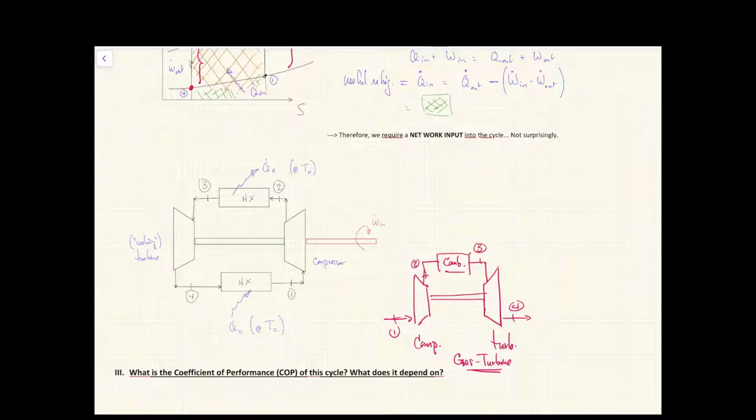So what we're going to do is take some of that air that comes into the turbine, tap it out at some intermediate stage within the turbine, and that's what we're going to use to go into the initial compressor. So the diagram that I have here is an idealized representation of a closed cycle doing this. But in practice, we don't have this heat exchanger on the cool side here. We're simply taking air coming in from the gas turbine engine, and that is my effective state 1 for the air cycle machine.